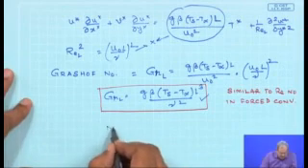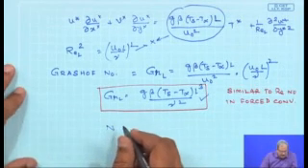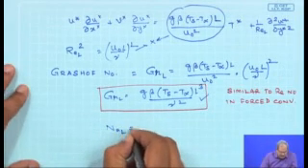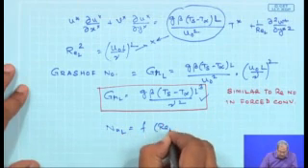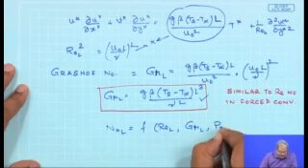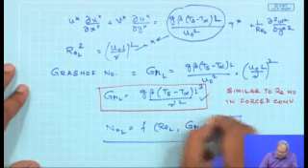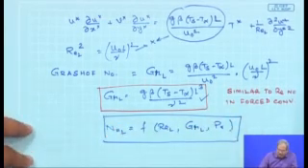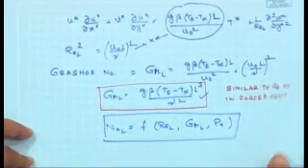So, the Nusselt number based on the length is a function of Reynolds number based on the length, Grashof number based on the entire length, and Prandtl number. This is what we should expect for any relation in natural convection.